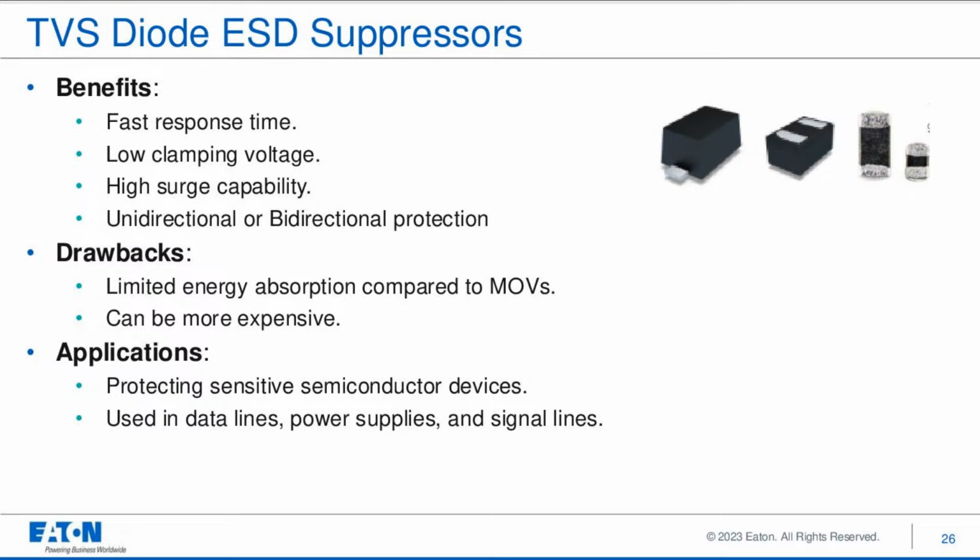Compared to MOVs, TVS diodes have a lower energy absorption capacity, but are generally applied after the input voltage protection and before the components to be protected, so that the clamping voltage can be closely sized to the downstream device's voltage withstand capabilities. With larger transients handled at the input, TVS diodes are often relied on for their precise clamping voltage to maintain an accurate voltage for sensitive ICs. For circuits with multiple data and signal lines needing protection, such as HDMI and USB, TVS diodes are also available with multiple channels on a single chip.